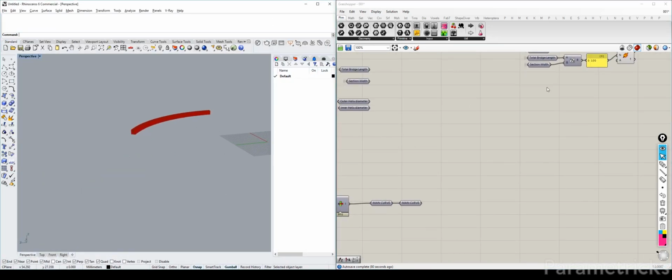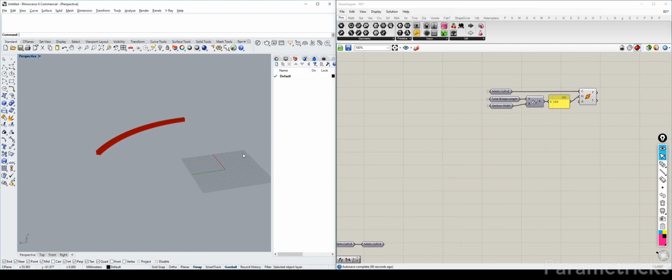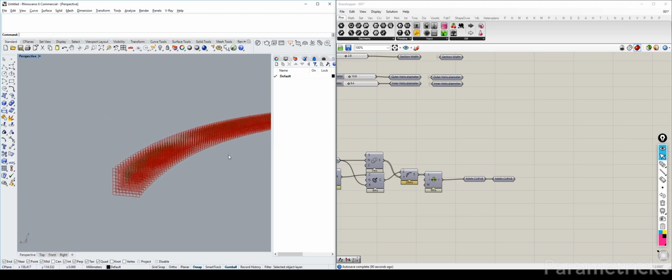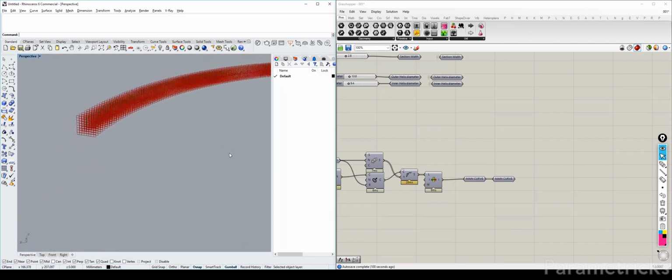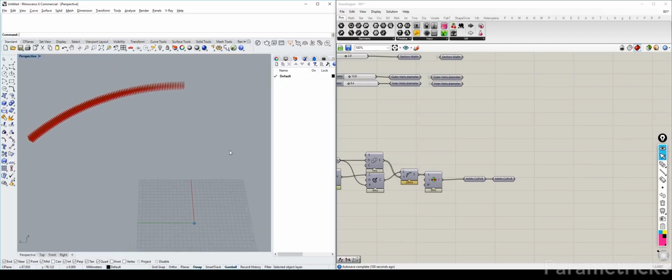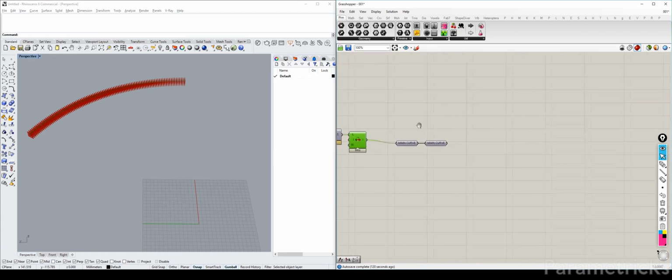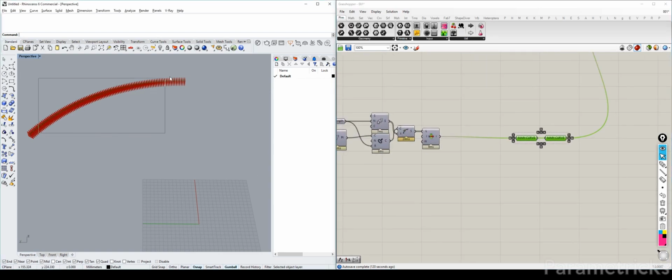Before we get back to the I-beams, something I like to do is, I'm using this 3D mouse, and as you can see, moving around is quite okay, but when the geometry itself gets further away from the origin, weird things can happen. And the same goes for moving around. So what I want to do is move this as close to the origin as I can.